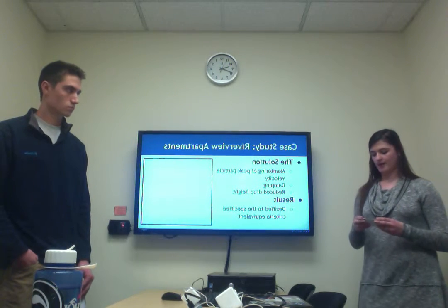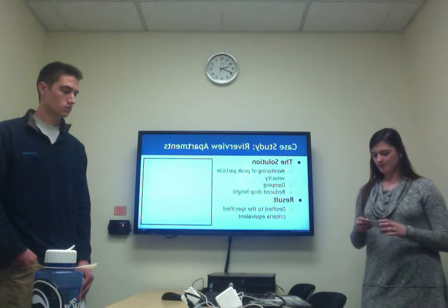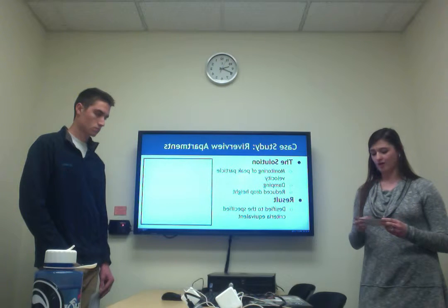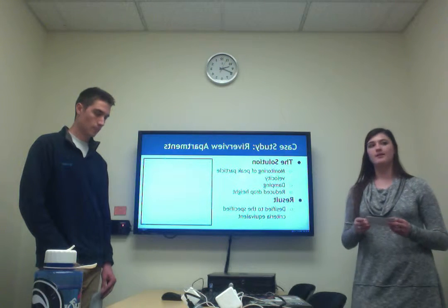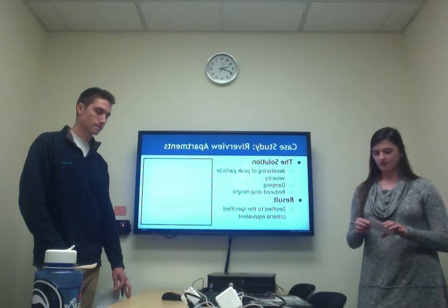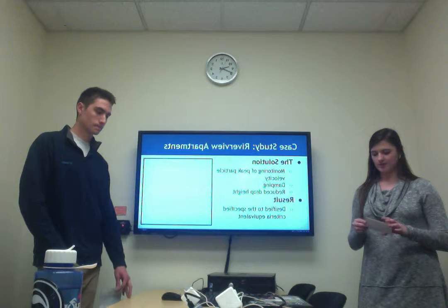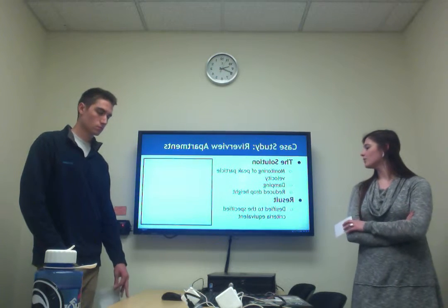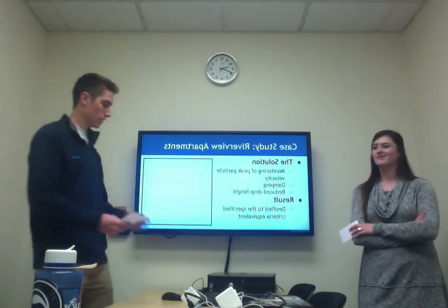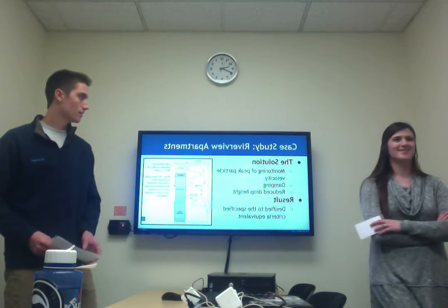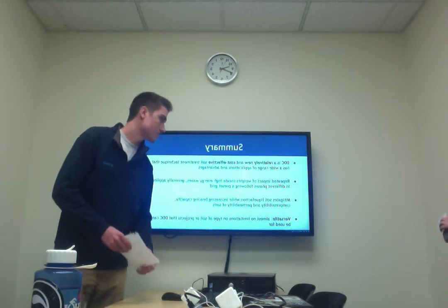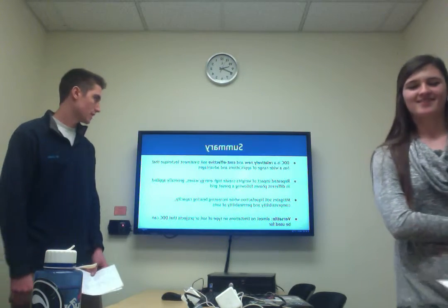And at the end, they used a cone penetrometer test, which is like what we did in lab, and they realized that they densified to the specific criteria equivalent of the 25 of the standard Proctor test. This is the picture. This leads us to the summary of our presentation.